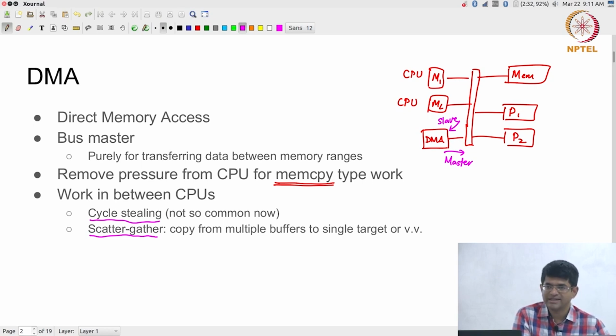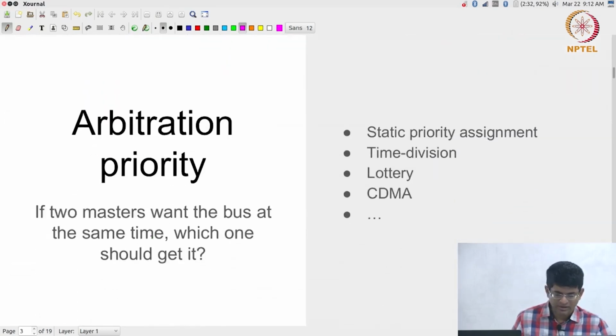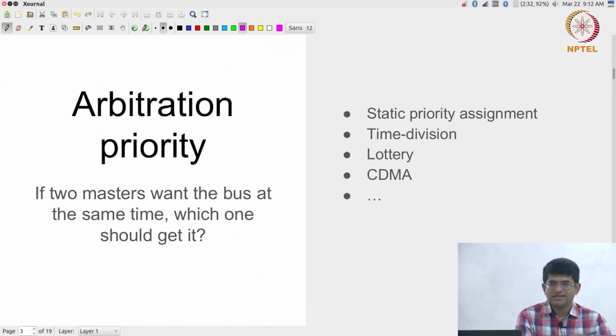That's because the AXI Lite is not using DMA and is not managing to get a throughput of 1 data word per cycle. Whereas by using DMA, you can actually improve those speeds to that point. But using it is more complex. It can be done. That's part of what you will need to do in order to really get some benefits in the projects that you are doing. Okay. All right. Now, this all raises one interesting question.